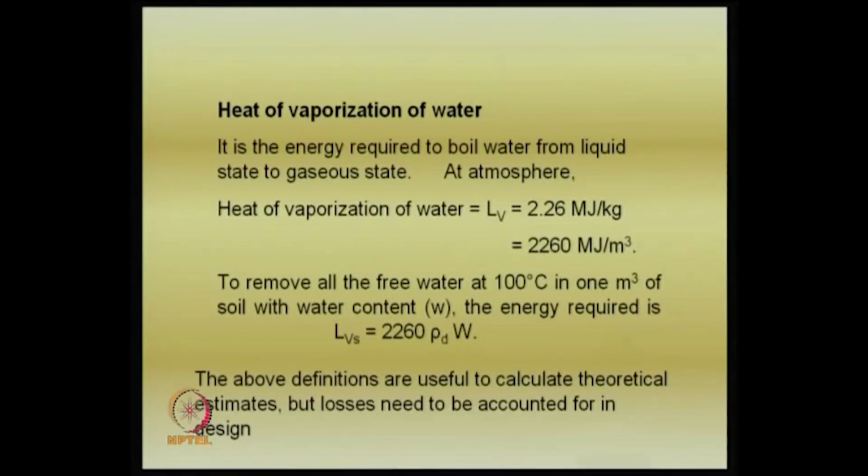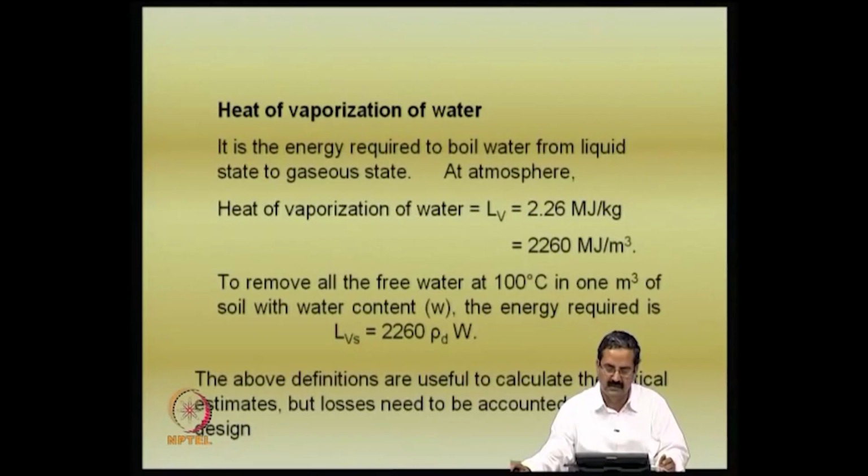The intact strength of the brick is going to be very high because of the heating. In what way does it help? It brings the particles together, and the water is also removed. That means it is going to be very stiff, and the stiffness values are going to be very good, so the settlements are going to be less and all that. So these definitions one should make use of.